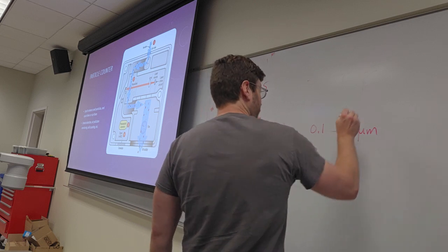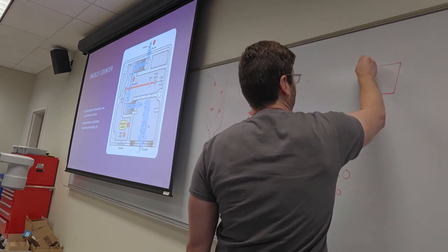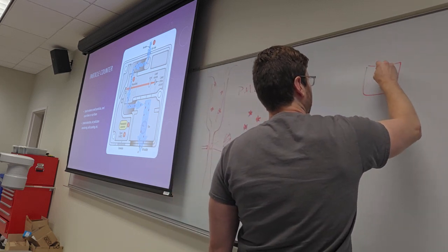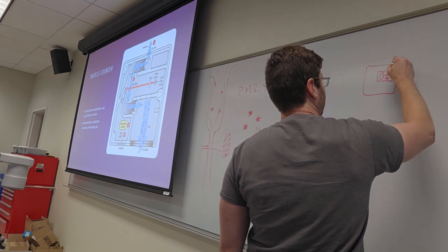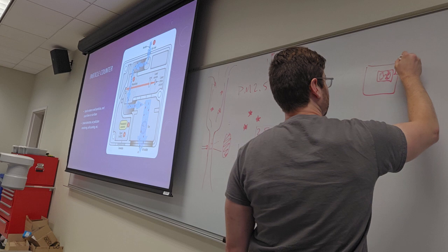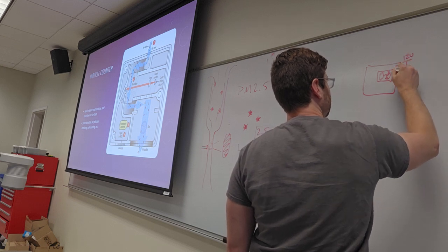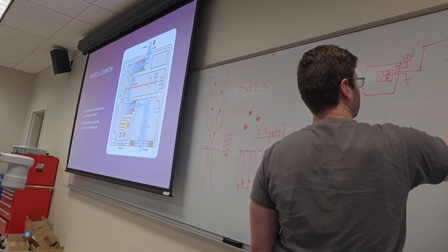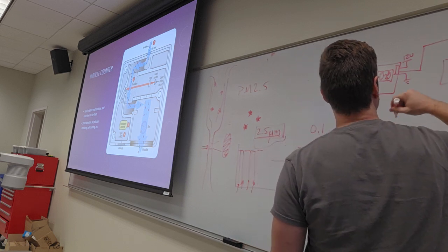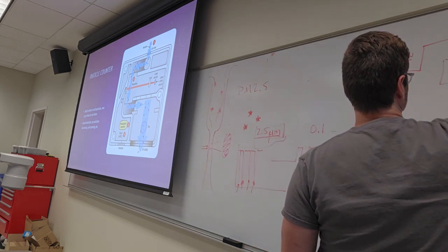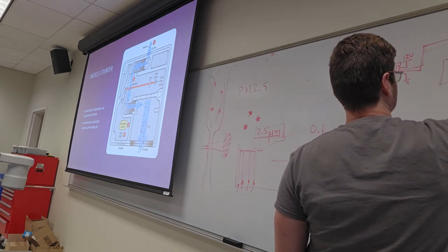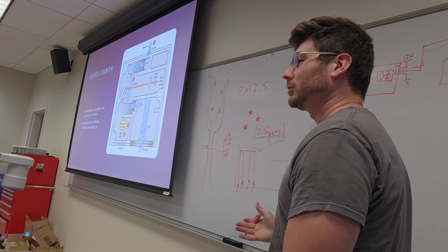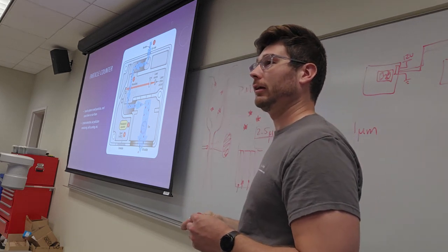But the device would just be a small device with a little fan, right? And then it would have a small connector on it. That connector, again, would have like 12 volts, ground, and then a data line that would go into your PLC. And that data line would probably be called a UART. If they had another data line, that would be I2C, or SPI, and so on. Right, that's how you actually get the data out of there.